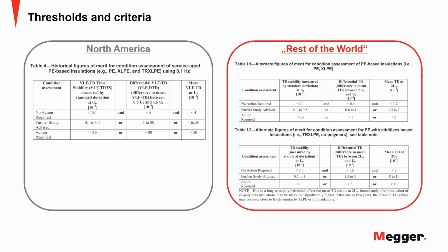Now, that question is a little bit loaded because it says leakage current between three phases. If I have a cable, and basically all modern medium voltage cables, every phase of a three-phase cable, even if it's a three-core cable, has its own neutral. So the leakage current of one phase does not really have anything to do with the leakage current of the other phases, okay?